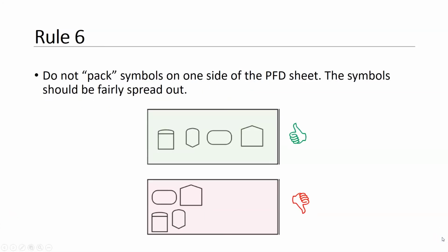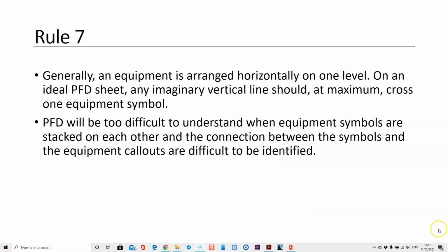Rule number 6. Do not pack symbols on one side of the PFD sheet. The symbols should be fairly spread out throughout your working area. Avoid cluttering your PFD sheet. It should be uncluttered, clear and easy to follow.